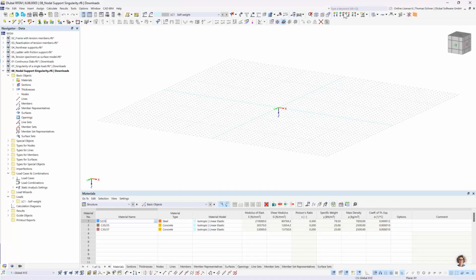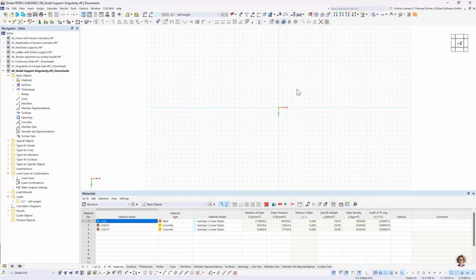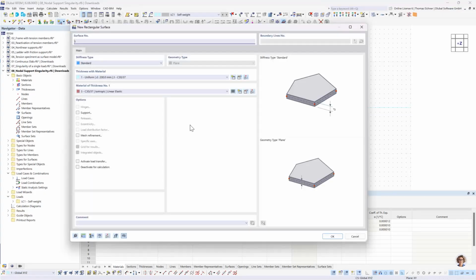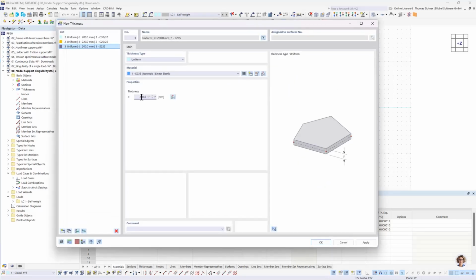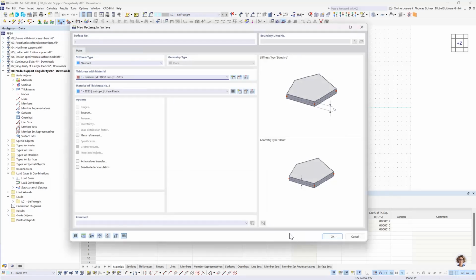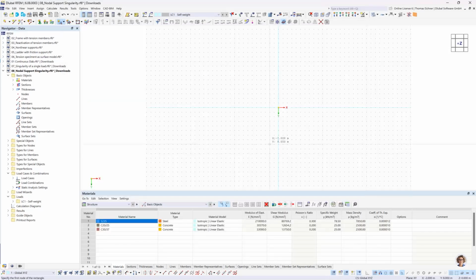And there it is. Again, we're gonna go for 4 slabs here. Let's just start right away. This time it's quite easy. The only thing I wanna change is here. I wanna go for 300 millimeters again. Okay. And stay with these C30/37. Press OK.